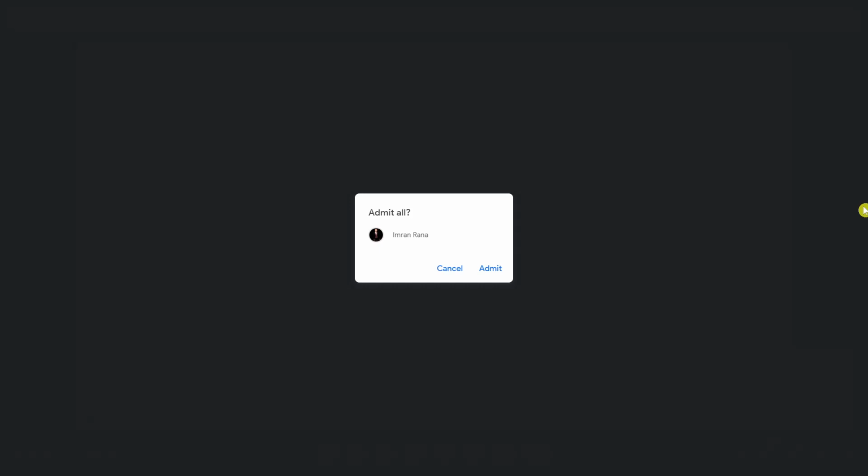The thing is, if I have to do it manually, I have to keep track and update this parameter as well every time I do it. But if I do it with Dynamo, I can simply go over here and click run again. And now if I select this, you can see it's automatically updated. If I want to change balcony to something else, say large balcony or something like that, just as an example, some information changes. I simply just need to go over here and run the script again. And you can see it will automatically change this data as well.